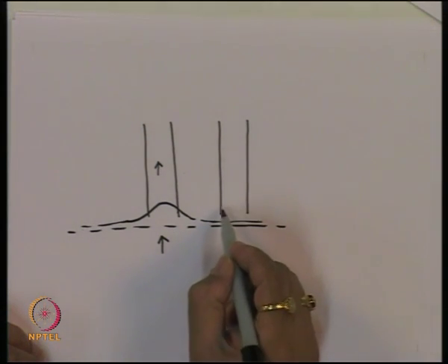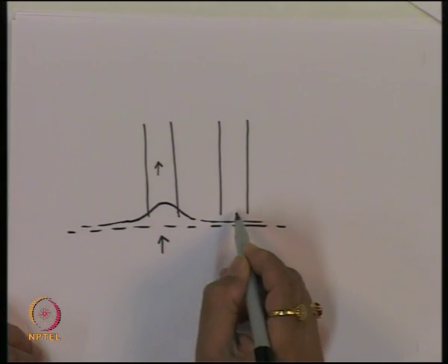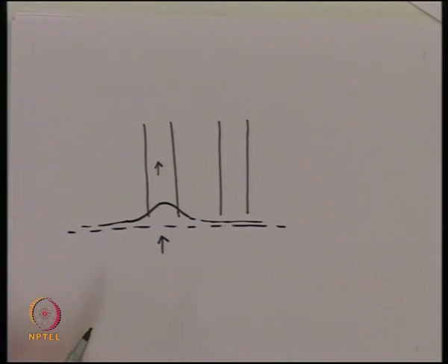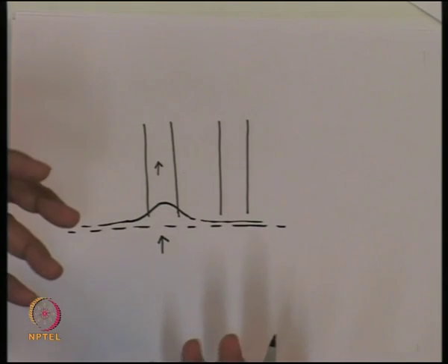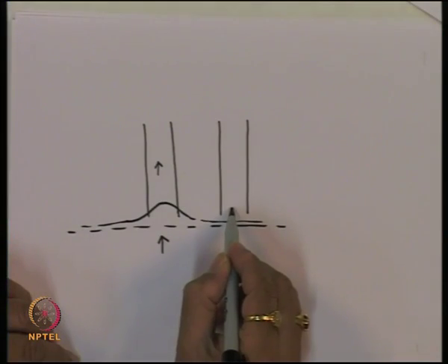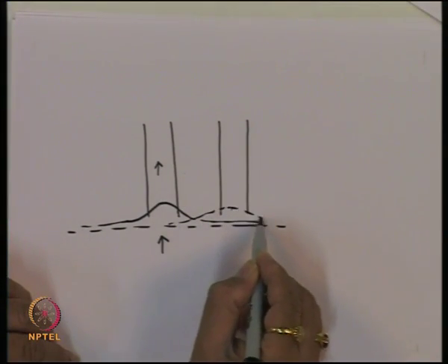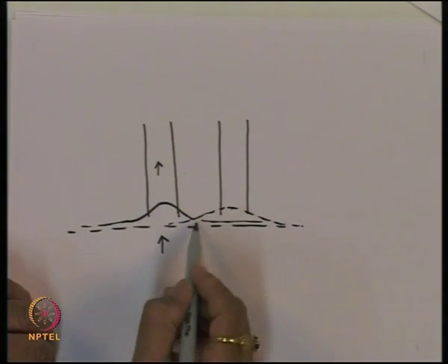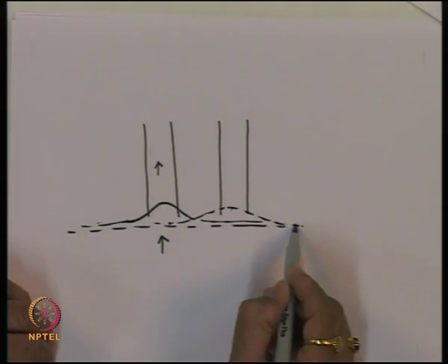So consequently some field will get induced inside this waveguide. But since this waveguide is a guiding structure and is identical to this, any arbitrary field cannot be excited inside this structure. What you can excite inside the structure again is the modal distribution, which will again extend theoretically up to infinity.